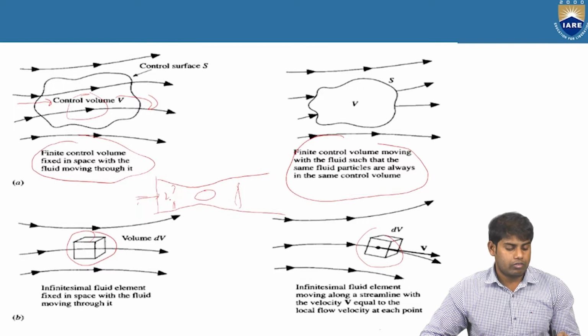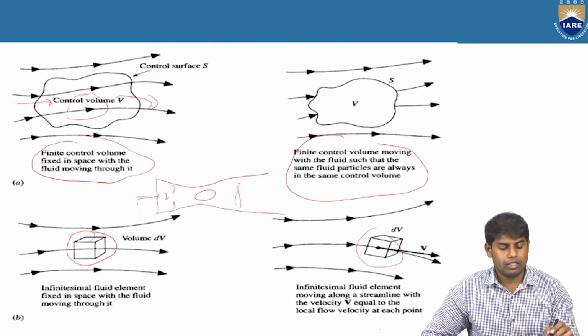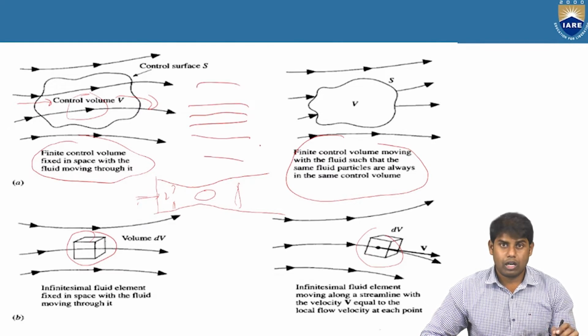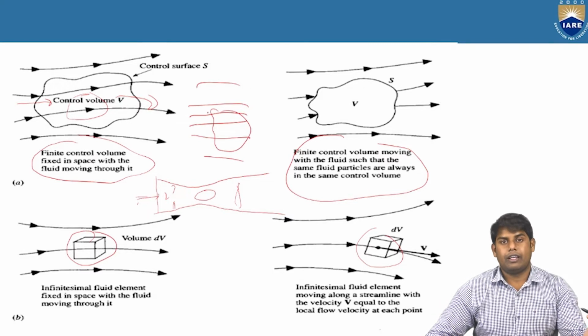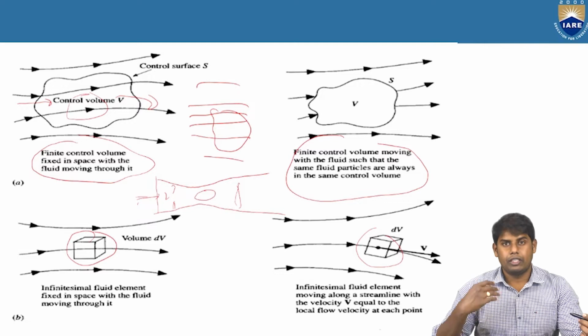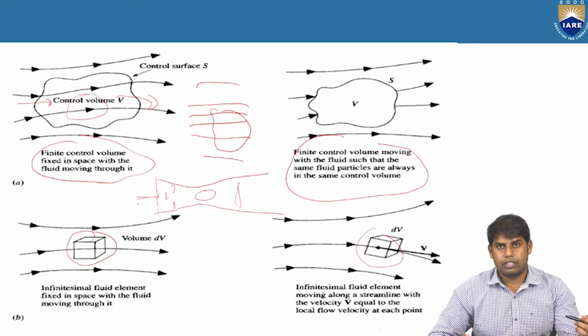So here you can see the control volume approach. The control volume is nothing but an entity where your area of study is limited to a certain region, and then you can extend it. What I mean is, let's say you have a flow in arbitrary space, so you can draw a control volume of any shape. There is no requirement that the control volume should be in this shape or that shape; there is no such restriction.